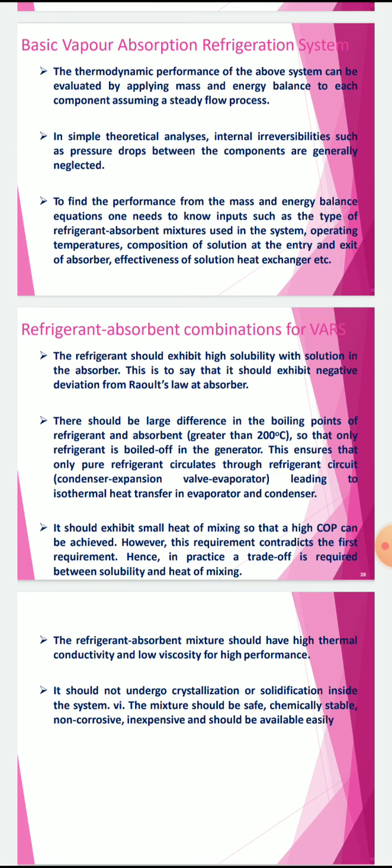Now, the refrigerant absorbent combinations for VAR. The refrigerant should exhibit high solubility with solution in the absorber. This is to say that it should exhibit negative deviation from Raoult's law at absorber.